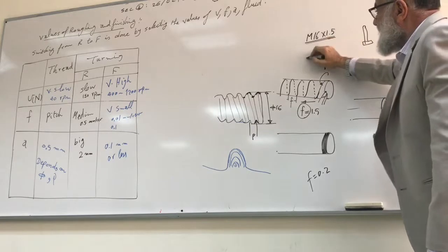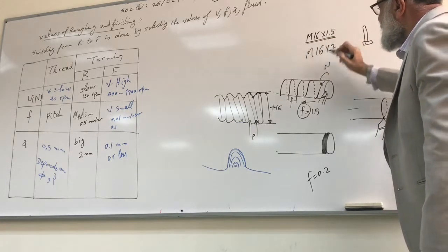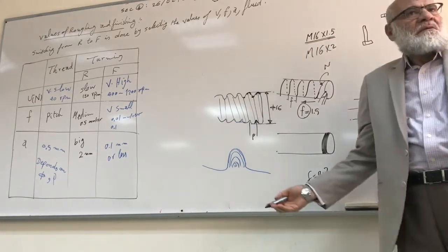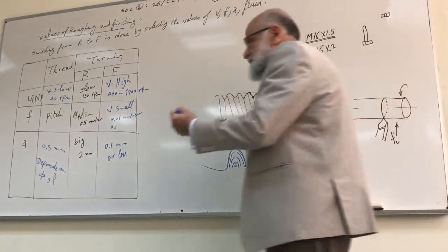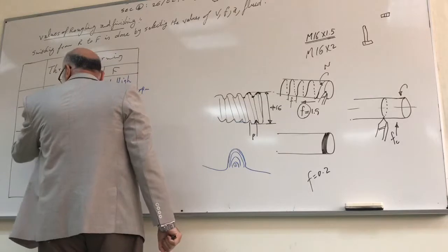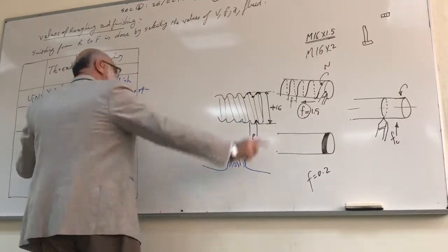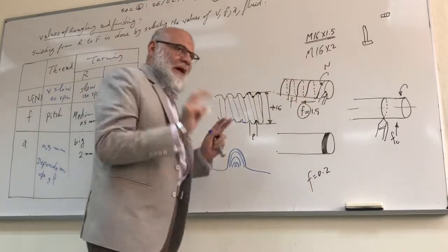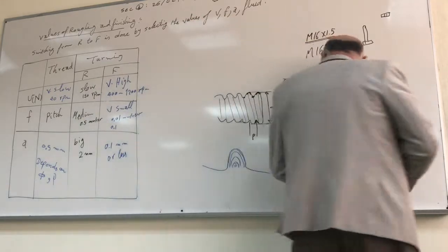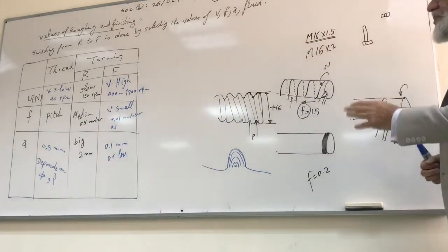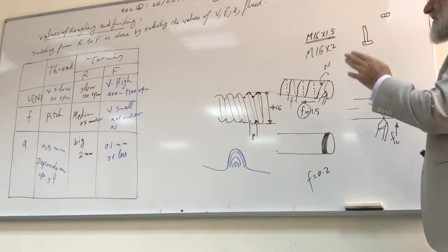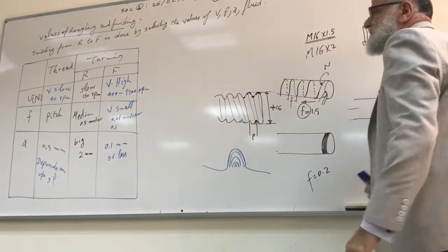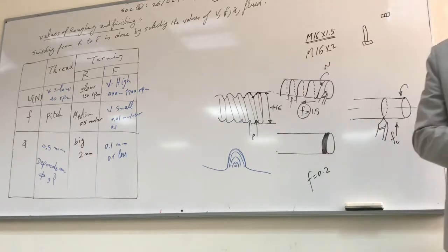But if there is another one, M16 2, fine, they will never be assembled. Never be assembled. So if you take the pitch or the feed as another value than 1.5, they won't fit together. Therefore, we say that the pitch should be taken equal to the pitch. The feed should be taken equal to the pitch in the case of threads. Is that clear, guys? Okay.